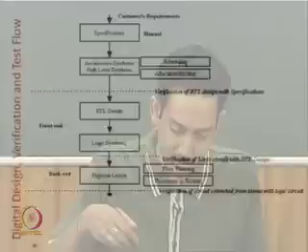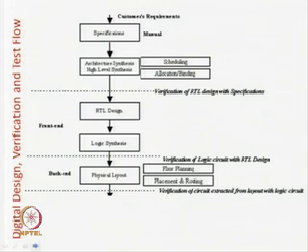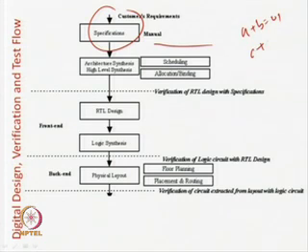So, let us see, this is the first part of digital VLSI design. First we have specifications. It is a manual level of specification, like you can say that A plus B equals out 1 and C plus D equals out 2. This can be a very simple case, where all these things are single bit numbers and O1 and O2 are the sum and carry bits, something like that. So, these are our design specifications, and that is done manually.